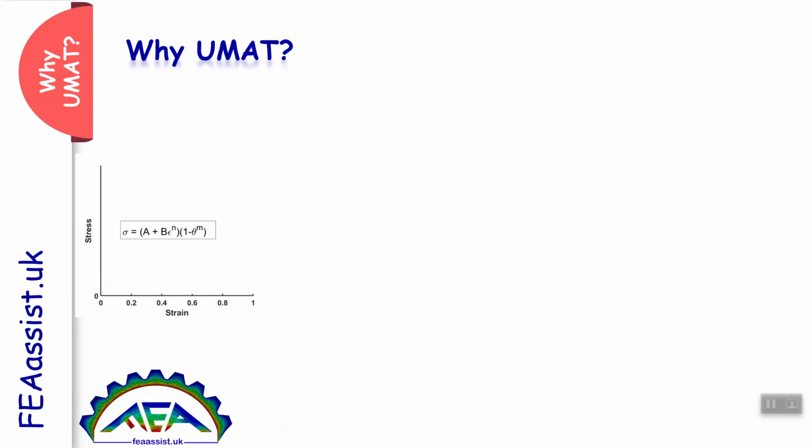If you want to solve your problem more precisely, then you need to have a constitutive equation, a constitutive behavior for your material. An equation in which the stress is a function of strain, temperature, and strain rate. In this example, we have a material that obeys the Johnson-Cook equation.